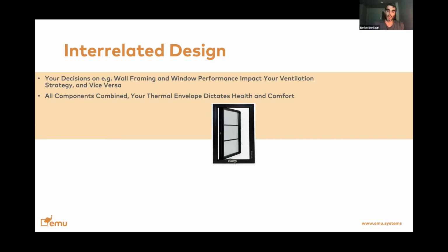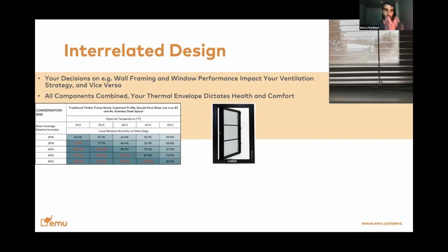That is not true. If you look at the table on the left-hand side, based on the temperature factor fRSI that we covered earlier on about the metal beam, that applies to any building component. If you look at this window, the code compliant window, it does comply with the 2018 IECC code, so you can use this in any building in climate zone 5.